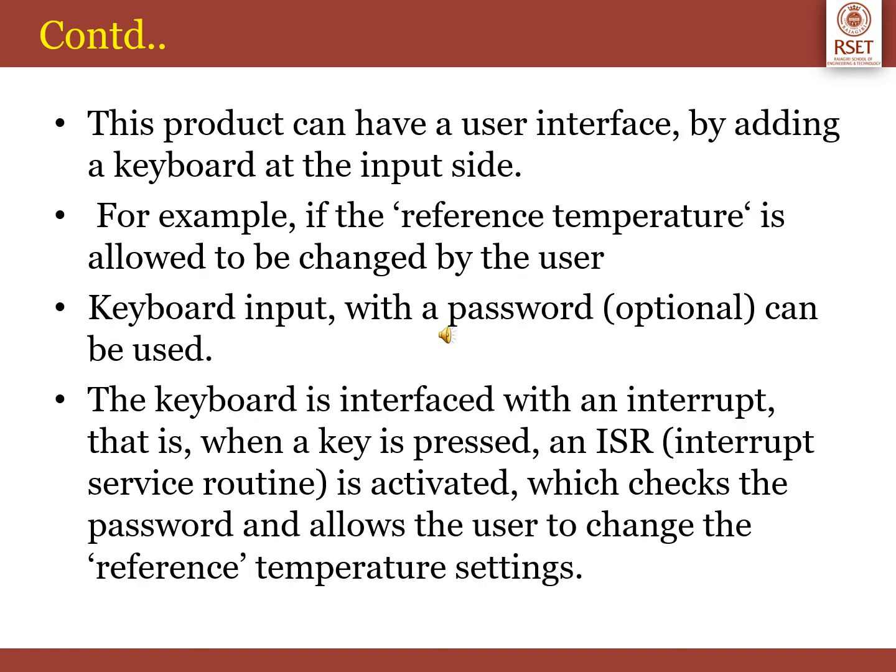The temperature monitor system can have a user interface by adding a keyboard at the input side. For example, if the reference temperature is allowed to be changed by the user, this keyboard, with a password, which is optional, can be used. The keyboard is interfaced with an interrupt, that is, when a key is pressed, the ISR, interrupt service routine, is activated, which checks the password and allows the user to change the reference temperature settings.